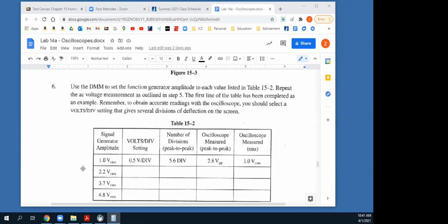Yep, I'm gonna zoom in on my scope here for a second. Hopefully this makes sense. First thing, when we're counting divisions, does it make sense to everybody that I've adjusted my vertical position, so I'm sitting on one of the lines in the lower peak?